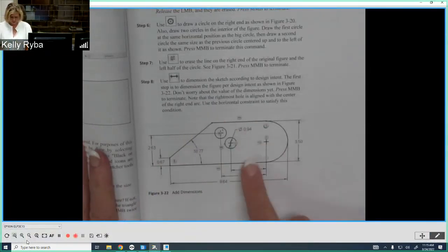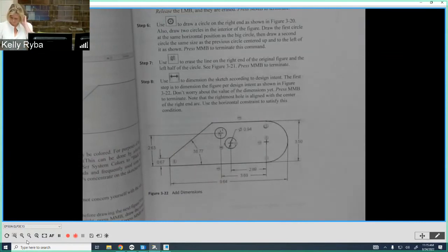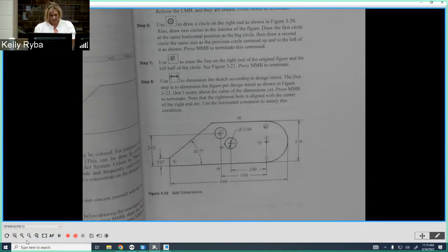So I'm going to kind of march around. Some of my dimensions might be okay, but some of them aren't. They're not coming from the same spot, the right spot that I want it to. And this has to do with how the part is designed, how it's going to be used later on, and what the relationships are that are important in its final form. So what's really cool about parametric software, no matter which one you're using, whether it's SolidWorks, Creo, CATIA, NX, Inventor, you get to, and the power is in, putting this design intent into your models, okay? So that they're gonna react the way you want them to and perform the way you want them to.